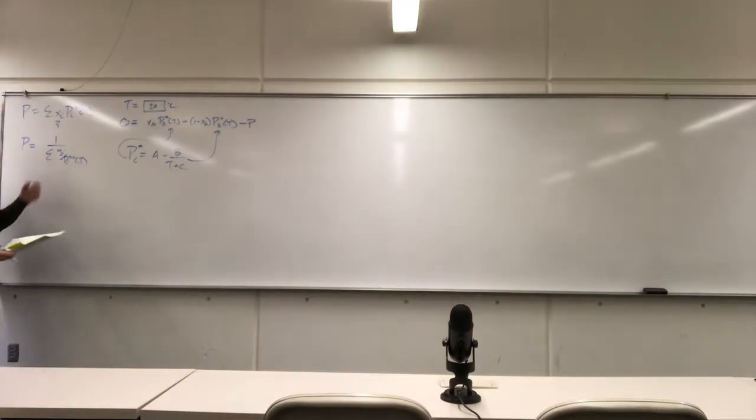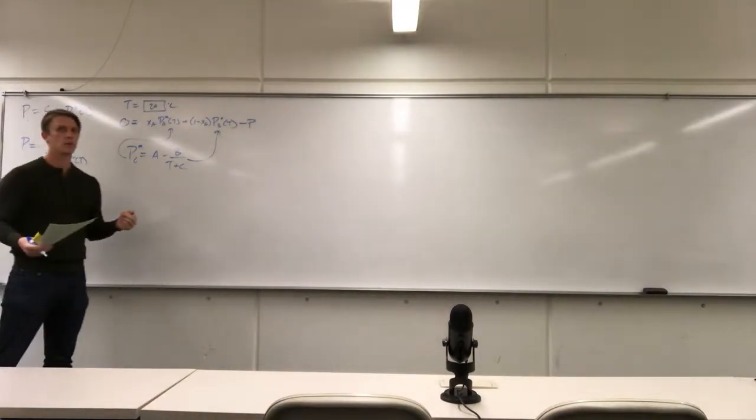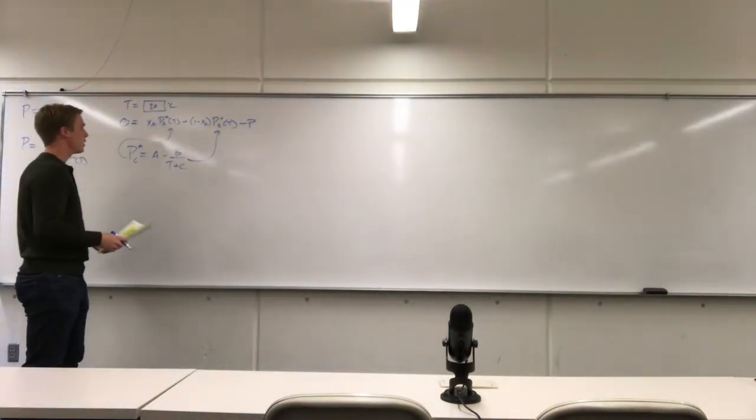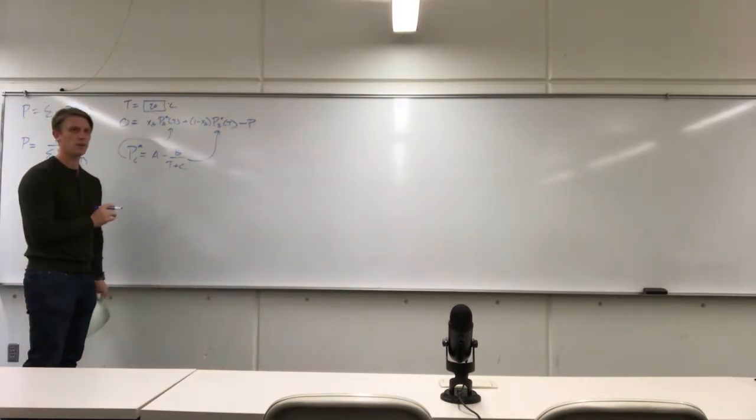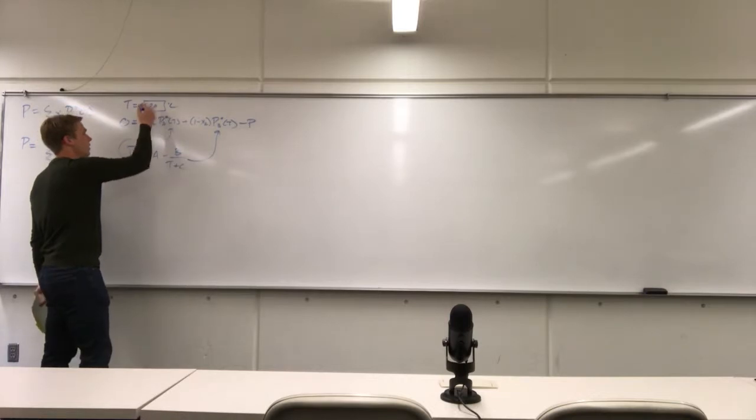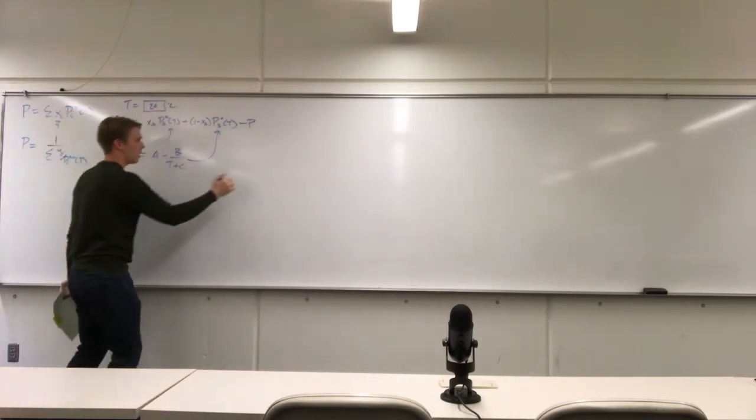Exactly the same formulation for the dew curve. Now, the other thing to note in Excel is that if you're trying to solve for a TXY diagram, this is somewhat tedious, right? Because you're basically going, vary this, do this, get the temperature, copy to the table.